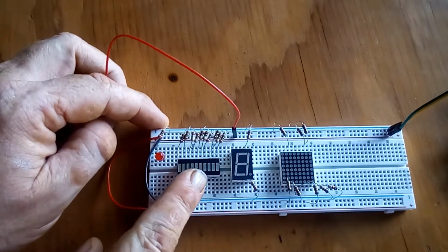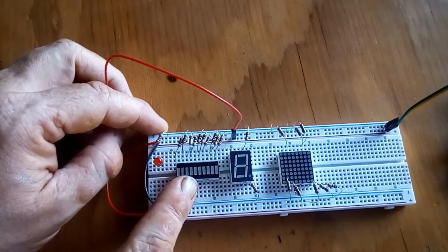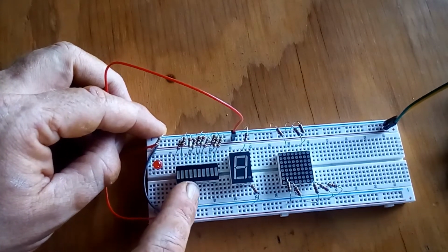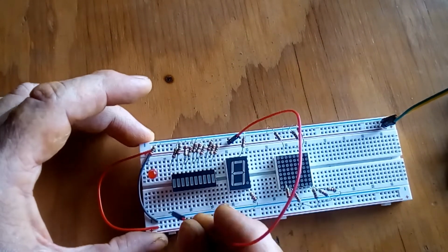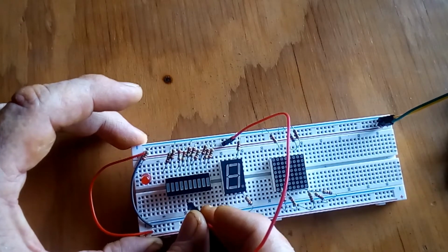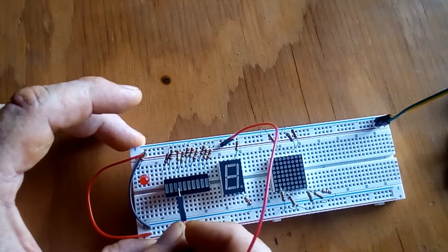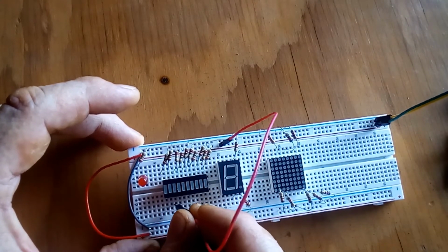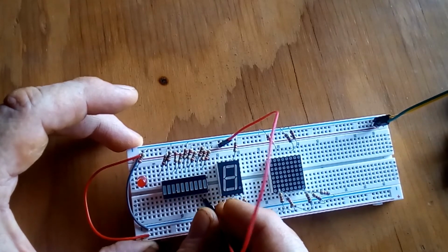The next one here, this is referred to as a bar graph, an LED bar graph. So it's basically 10 LEDs. So we can use them any way we want, but typically it shows output levels. So if we just start plugging them in, you can see it's 10 separate LEDs organized in a way that we can kind of show a level going up and down with that. Very straightforward, cathodes on one side, anodes on the other, and then we just form the connections.